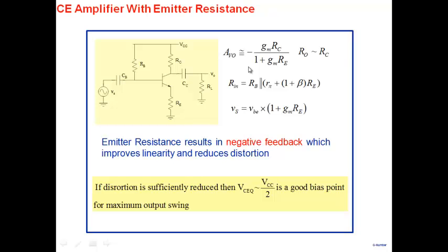Okay, so initial gain is 1000, you sacrifice the gain, bring it back to 100, and what do you get? You get all the other benefits that are there. Input resistance may go up, and depending on how you apply the negative feedback, you can reap the other benefits, bandwidth and other things that are there. So that's a strategy. That's the strategy behind an op-amp.